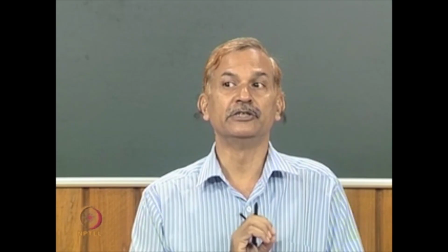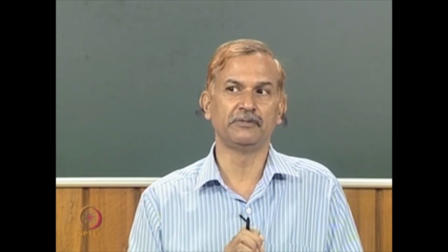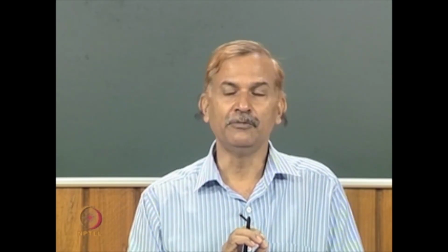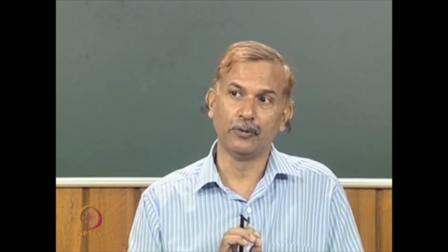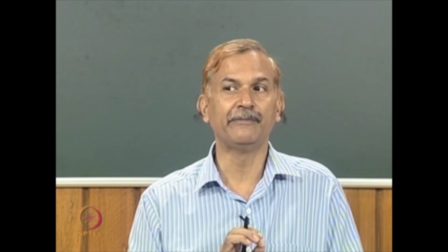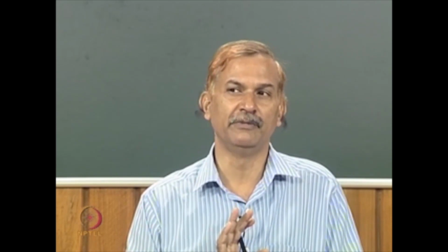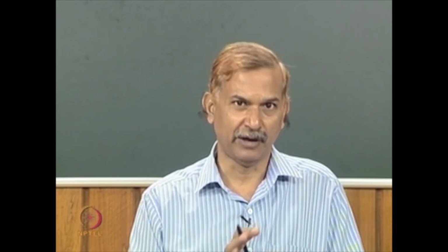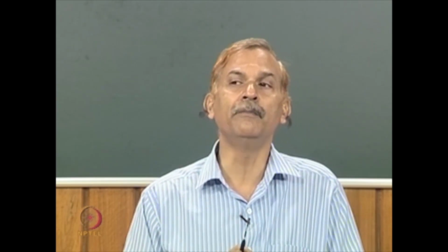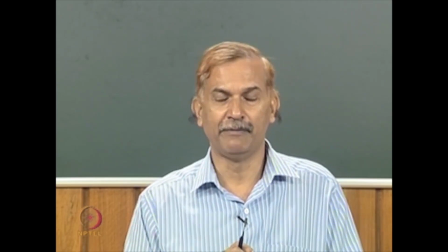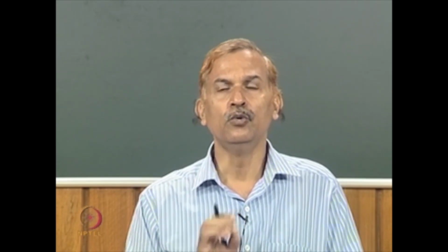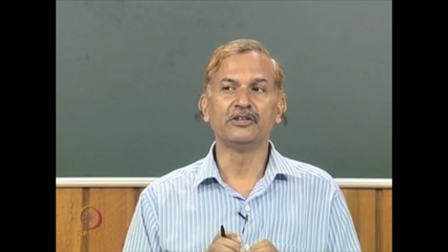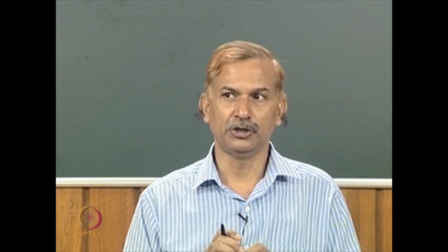Since it is a hard problem, currently we are using some heuristics, and with the help of this heuristic method, we will try to find some variable ordering which is going to give us some compact representation. The BDD that we are going to get may not be the minimal one, but it is going to give us some compact representation. So, we apply some heuristic, and by using it, we find some variable ordering, and after that we apply this variable ordering to construct the BDD. In most cases we have found that we are getting a reasonably good size of BDD representation of any function.